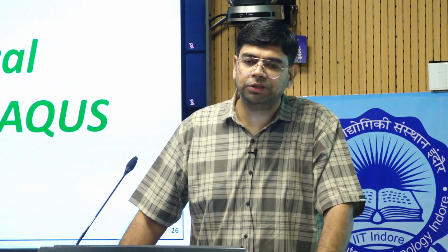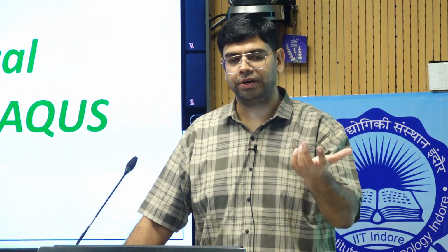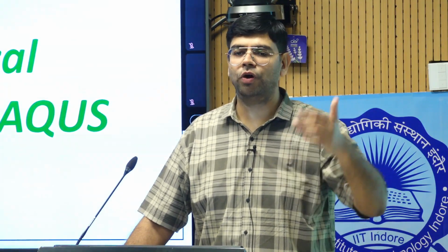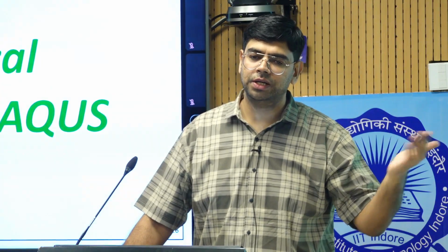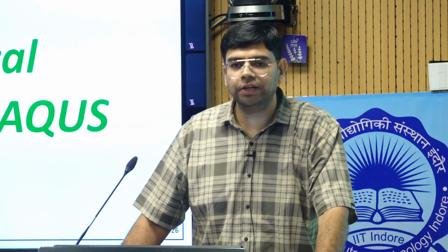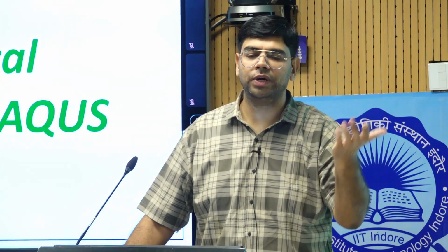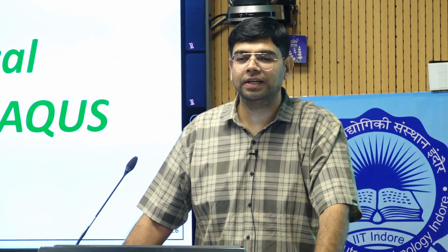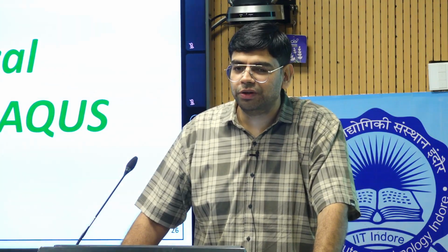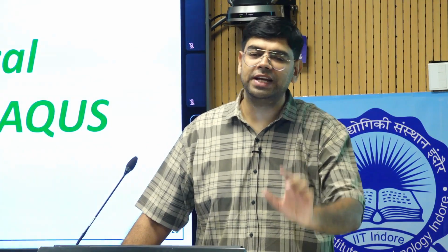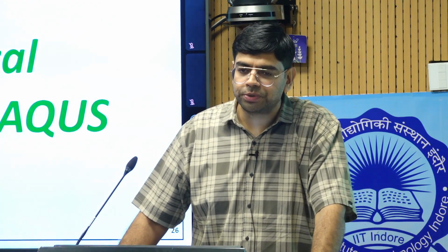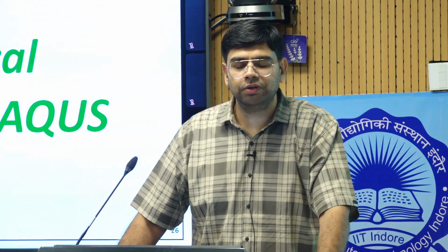Initially in finite element software, you develop the geometry. For example, if you want to model this DEA based actuator, you have to develop the geometry of the frame and define the membrane. Or in some software, you can develop the geometry in SolidWorks and directly import it. Sometimes a complicated geometry is very difficult to make in the Abaqus software, so you can easily make it in SolidWorks or AutoCAD, which you are already familiar with. There is an option to import that geometry directly into the finite element software. So that first step is very clear, I think.